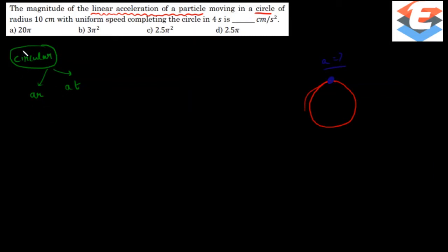If it is undergoing circular motion, then r will be constant, right? R will be constant. So r dot is 0, r double dot is 0. Which means one radial acceleration component has become 0. So only one radial acceleration will be left out. That is going to be minus r omega square, which is centripetal acceleration.